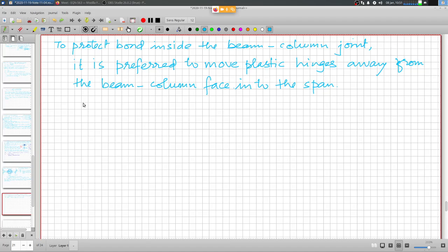Don't just blindly believe the results of your computer model analysis that are only central line models, and central line models do not account for the finite size of the beam column junction, and the fact that there is a finite width over which this moment reversal in the beams that are framing into that joint is happening, and that leads to a very high gradient, leading to very high shear force in the beam column junction,